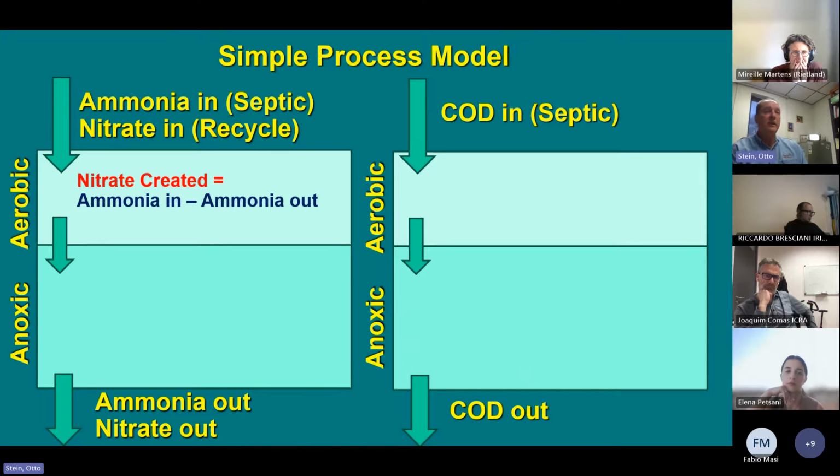We could estimate how much nitrate was removed by doing some stoichiometry and say that the COD removed by denitrification is 80% of the nitrate removed. And then we could make an estimate of the aerobic COD removed by what came in and what came out, minus how much was done by denitrification. So we've ignored a lot of other processes, but we focused on that.